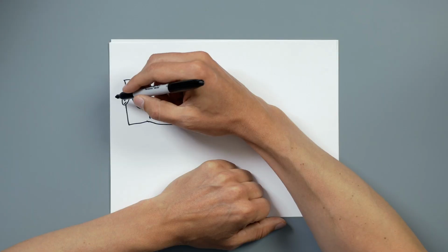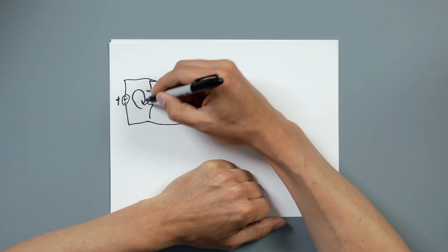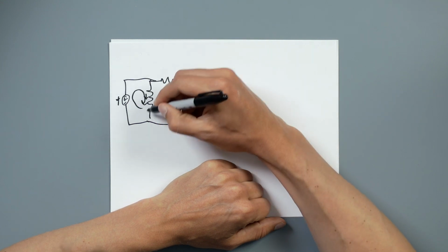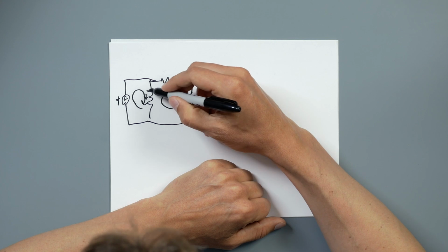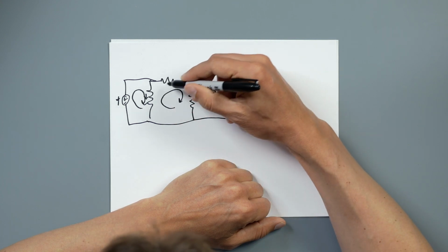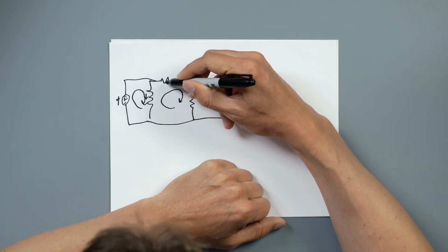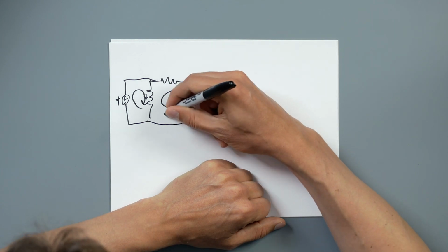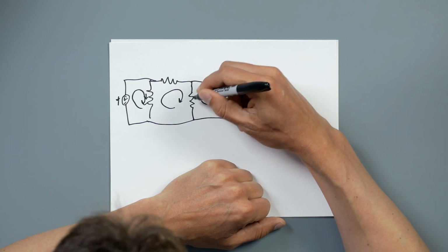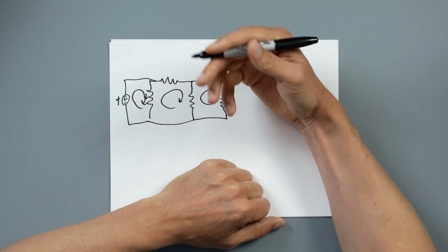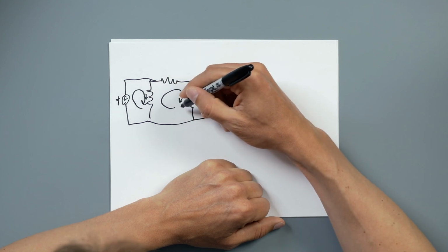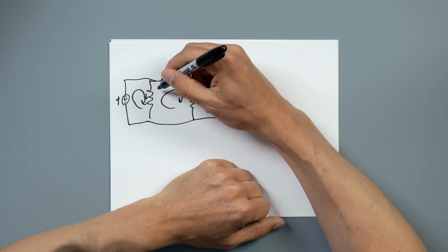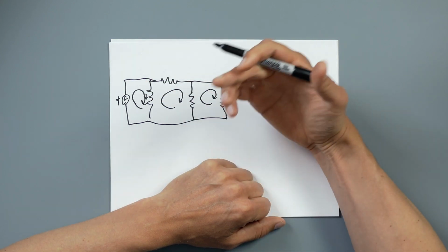Moving forward. As we go up in voltage across here, we can assume that we're going down in voltage right there. So the summation of the voltages up and down here is zero. And then since we're expecting a voltage drop here, we should be able to see that we are going to be increasing or dropping the voltage in such a way that all of the voltages across these three resistors are also equal to zero, and same with this one. And that is the basic premise: whatever mesh you have, the sum of all of the voltages up or down across the different elements should equal zero.